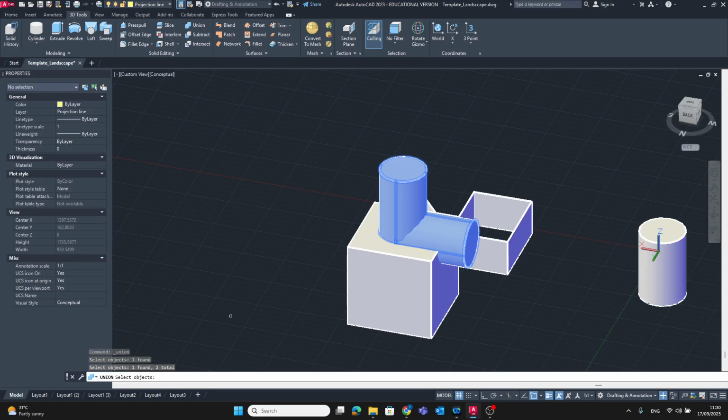If you forget to press shift, the problem is that if you click here and then click here, it cannot recognize every object that you have. So just make sure that you press shift as well. Now it is 2 in total. Press enter. Once you press enter, you're going to find the two cylinders connected into an L-shaped tube.